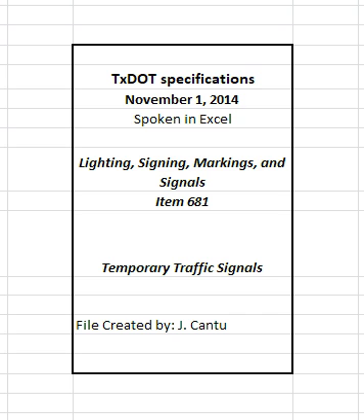shown on the plans. 3.1 Operation and maintenance. Maintain and operate the temporary traffic signals for the duration of the contract. The traffic signal timing plan will be provided by the department or local entity. Set signal timing as shown on the plans or as directed. Designate in writing a sufficiently skilled individual responsible for maintenance and operation of the temporary traffic signals who is available to respond within a reasonable time, 24 hours each day, unless otherwise shown on the plans. Provide backup power for each location at all times, when shown on the plans.